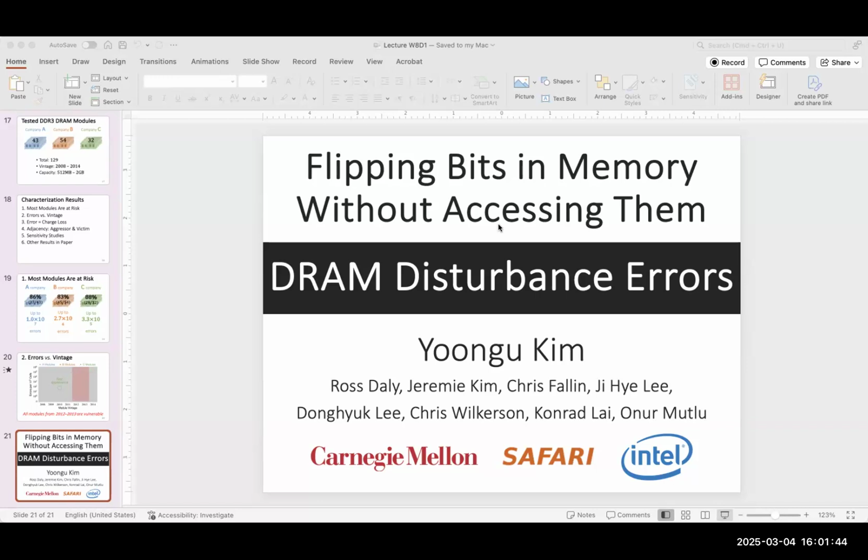Now it is from 0 to 3 volt, and everything is accordingly reduced in size, including your noise margins, like to 0.25 volt, 0.8. But reducing the noise margins means reducing the reliability. It is now relatively easier to do the bit flips. So this is how scaling down transistors affects the noise margin and reliability.